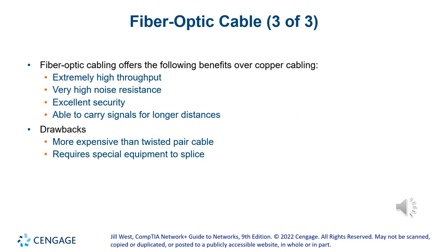We have some of the optics here at the college that can easily go 80 kilometers, and others can go further. It depends on the intensity of the laser. The stronger the laser, the further you can go. We'll talk about that later. There are multiple types of lasers, and the price is not much different. You can get one of the modules that has a stronger laser with a different wavelength. That wavelength is able to go further because it is a brighter laser than the others. So you can go, like I said, for long distances.